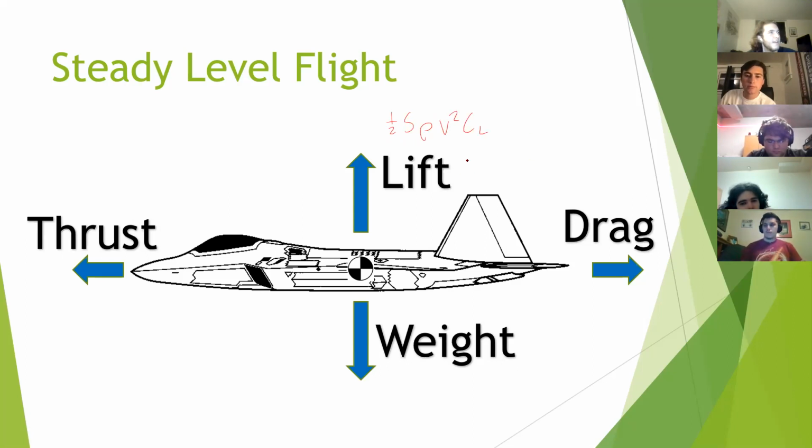Yeah, exactly. I probably put those all in an order that you're not gonna like, but I can find something better for you to not like. I would just move that over there. Other than that, you're chilling. Q is your dynamic pressure, which is 1/2 rho V squared, which is just a thing that we deal with a lot, and so we like to keep those terms together. But other than that, it doesn't really matter. Right, yeah. And then what about drag? Same thing, but swap it for coefficient of drag. Yeah, exactly. I'm doing your order, whatever.